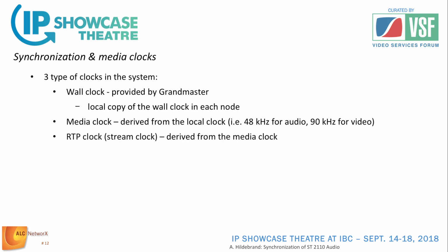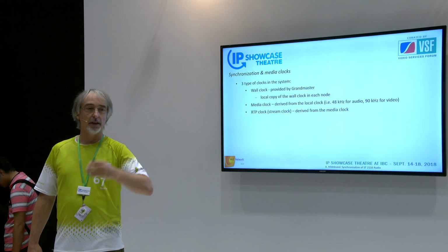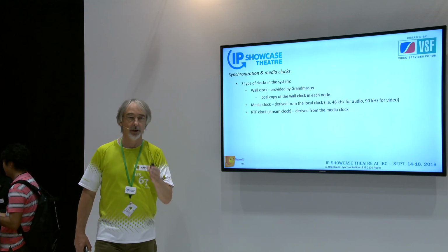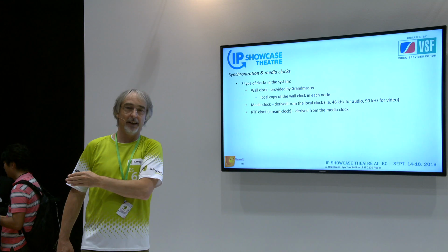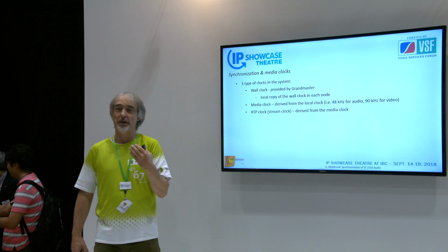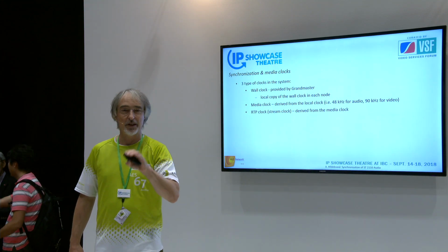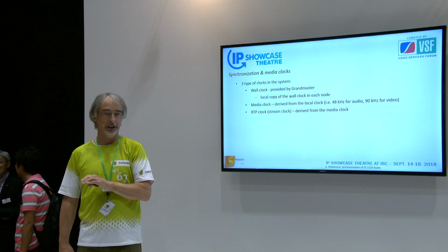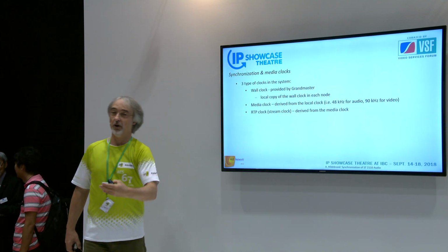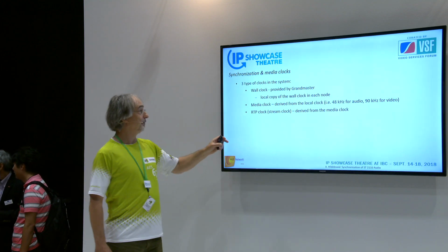And then we have the stream clock, yet another clock, because RTP, as the transport protocol, has RTP timestamps with linear audio. It's indicating the precise timestamp of the first sample in that RTP packet. And nicely enough, we don't have to put PTP timestamps in there, because with linear audio, the timestamp is formatted as a clock counter. So we have 32 bits of timestamp. We'll explain that in a minute. We count clock counts actually here.